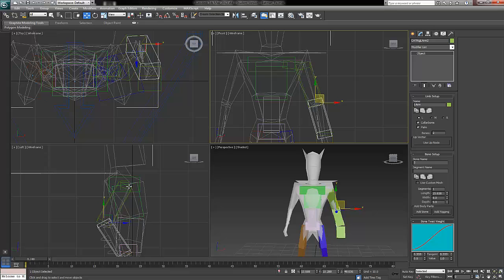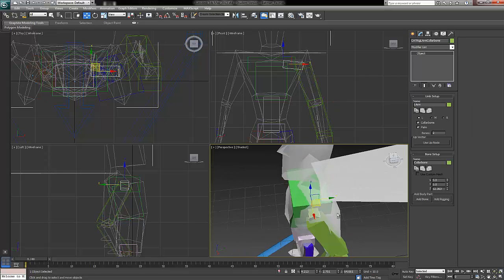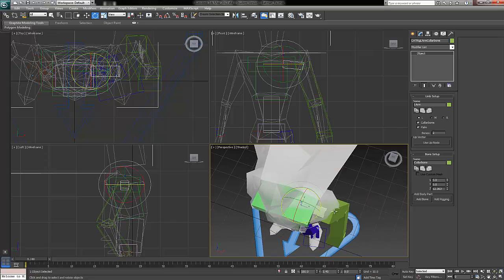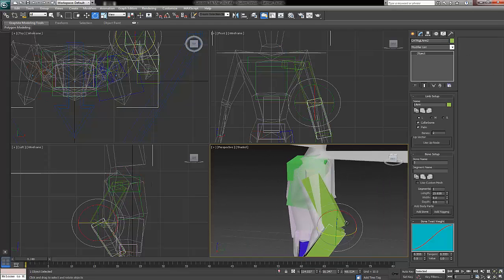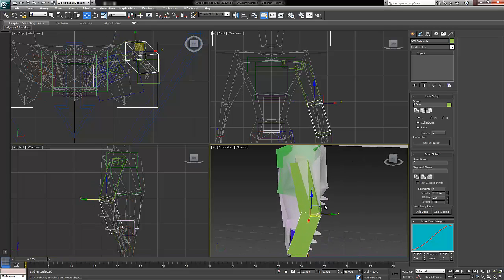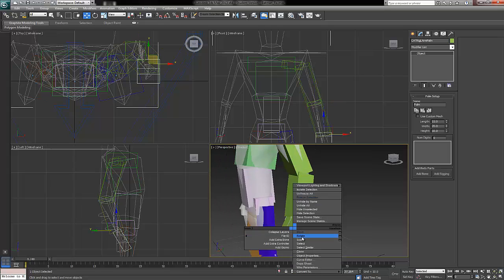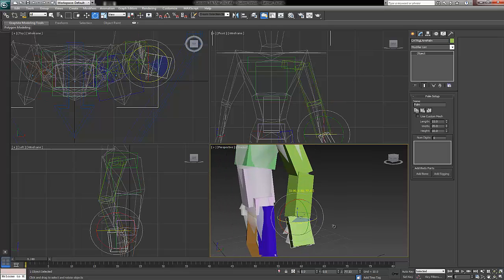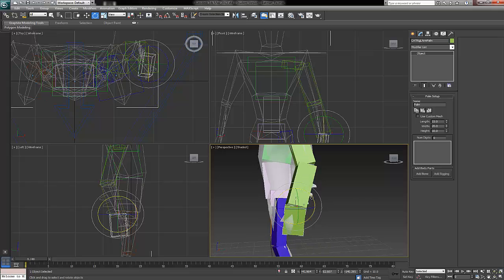Now you notice that this model sticks out with its chest, so its shoulders are set back a bit. So I need to rotate the shoulder joint to make sure it simulates that, which requires me to readjust the arms a bit. And this is why it's good working in all 4 viewports, because it speeds up your workflow and makes it easier. Now my palm's facing the wrong way, so I need to rotate this around to get it facing the correct way. For the purpose of this tutorial, I'm not going to add fingers. I'm just going to keep with a basic palm bone.